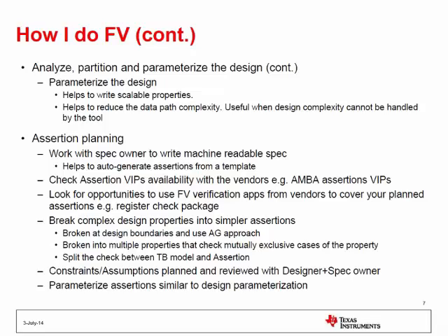And last, one of the important points, which I keep stressing, because usually when I talk to RTL verification folks, they say, boss, you cannot do this because it takes end to end and you need to write a very complex property for it. I keep stressing that if you are able to partition and then pipeline your assertion, you will actually be writing very simple assertions, not just one line, but 5 or 6 assertions, and you will still be able to meet the whole goal of the end-to-end assertion.